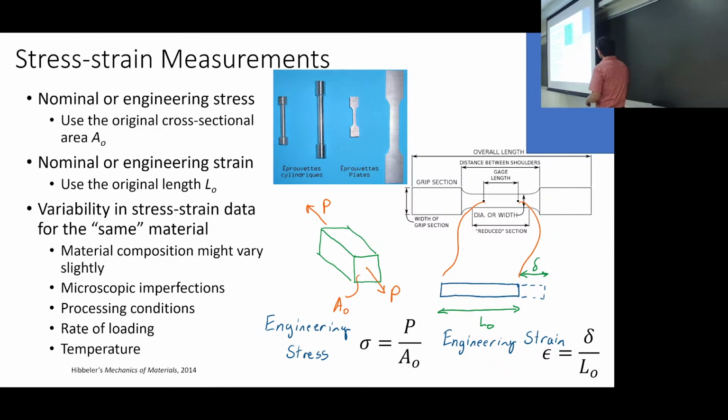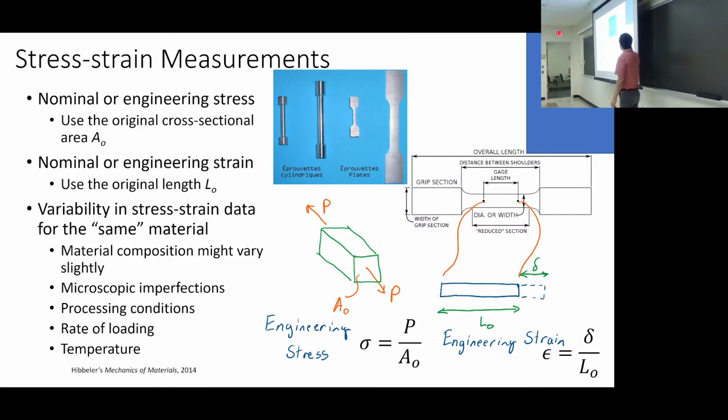Another nuanced thing that you'll cover more in a later course is the reason these have arcs here: we want to avoid what are called stress concentrations. Another tidbit: when you design a component, it's often a bad idea to put sharp edges in it, for multiple reasons.